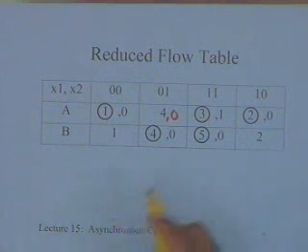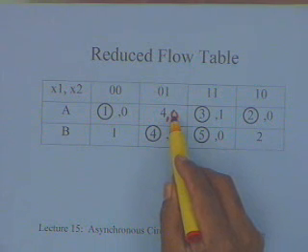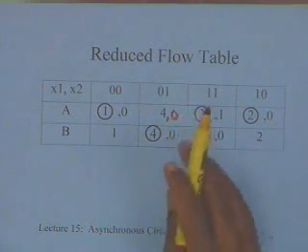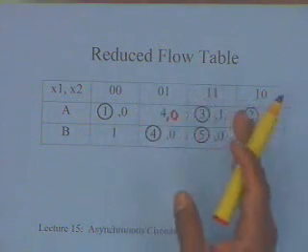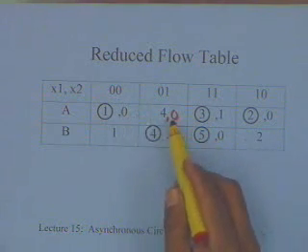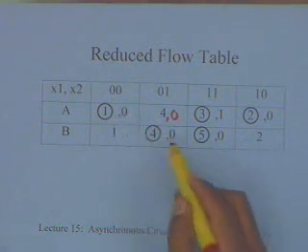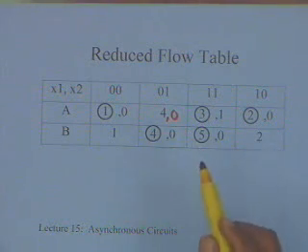What you should not do is, for example, assign an output of 1 here, because the implication is it will generate a completely unwanted pulse. It will go through a transient state which actually gives you output of 1 and then go to 0. So you can either assign it with this or assign it with this, but anyway here we assign it with 0.